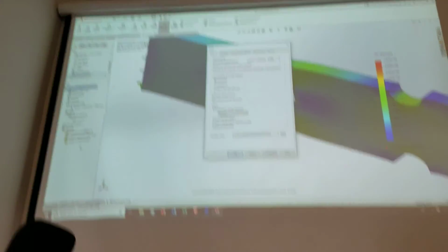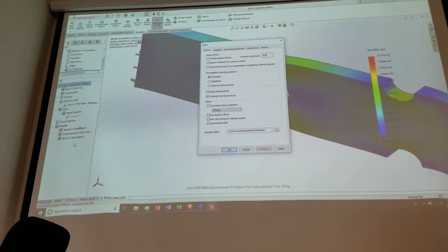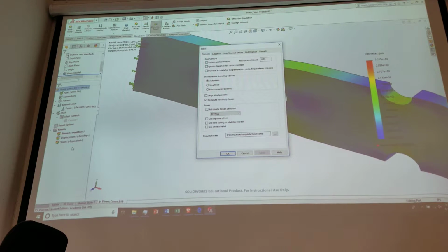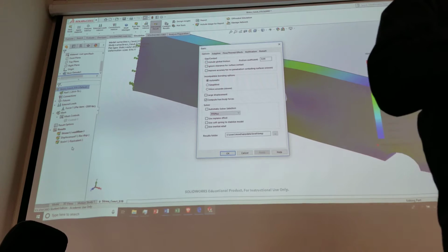That's all relationship, and that's a huge system of simultaneous equations, but it's a very sparse matrix. It's almost always on the center diagonal because the nodes are related to each other, and so most of the terms are 0 because most of the nodes aren't connected to each other, right? Most of the equations are only between nodes that are close to each other, that are basically connected in the form of an element. And so you wind up with this huge matrix that's thousands by thousands, but most of it's zeros, because the nodes aren't connected to each other. There's no mathematical relationship between most of the nodes. It's just the ones that are connected in elements.